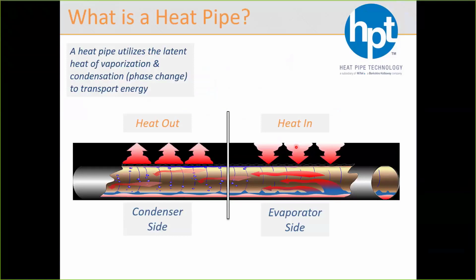In our case, we use half-inch copper tubes, and inside you have a working fluid. What we use here is either 134A or 410A. If you take a look at this graphic, as you apply heat to one side, the refrigerant inside, which is in a liquid state, absorbs that heat, boils or vaporizes, and travels over to the cold side, where it rejects the heat to the surroundings. After that, it condenses, comes back around, and the cycle continues over and over again.